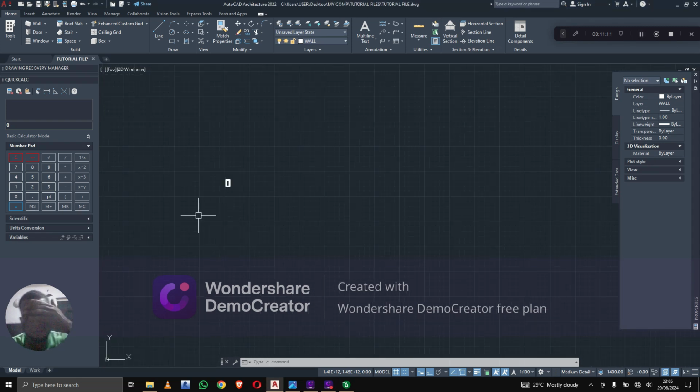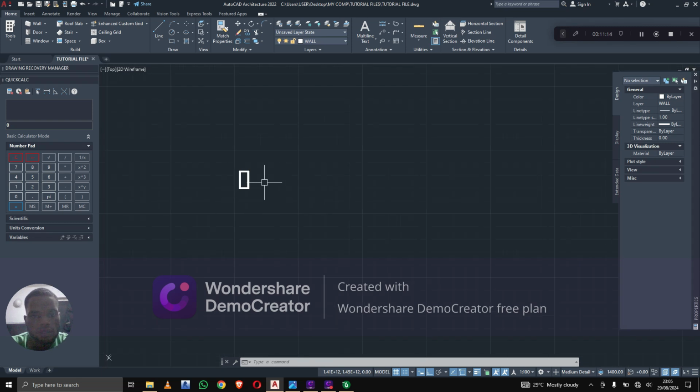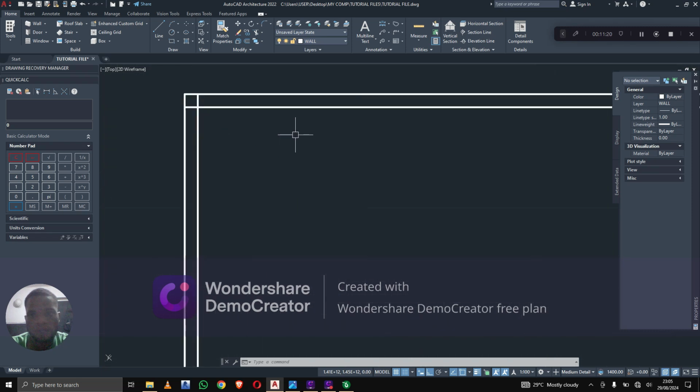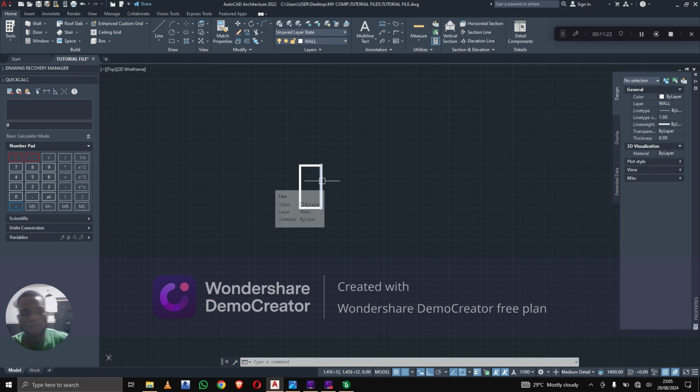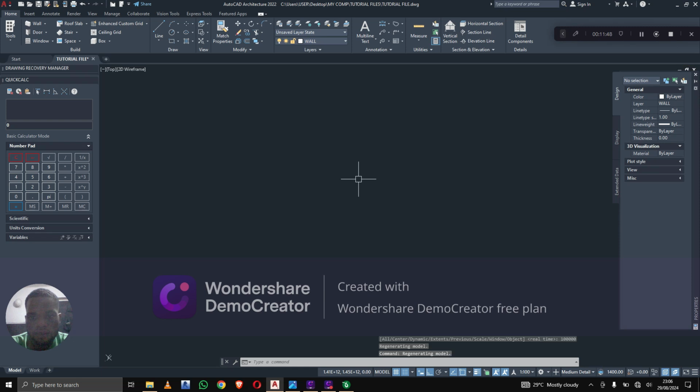The thing is that I didn't set the zoom. So if your system is behaving like that as well, just type zoom on your keyboard, enter, and input maybe 100,000. You might not be able to get to that kind of meter, so just use 100,000 millimeters. It will bring you to this, and by that you can easily draw whatever you want to draw now.